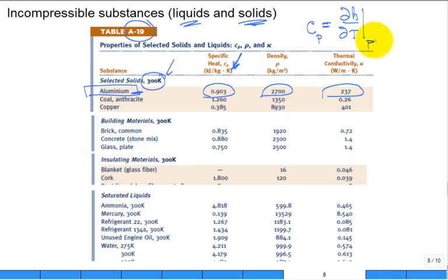So you want to find out how much heat goes into the system. Let's say Q in typically is related to a change in H. So that'll be C sub P delta T. How much temperature change was there? What's the value of specific heat? That's how much heat had to come in, or if you know how much heat comes in, that's the temperature rise that you expect. All right.